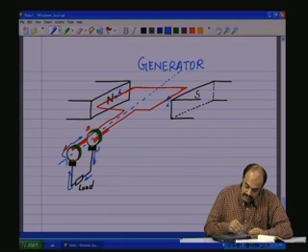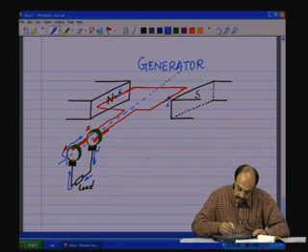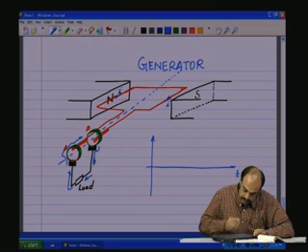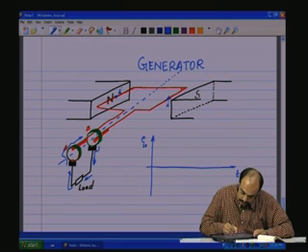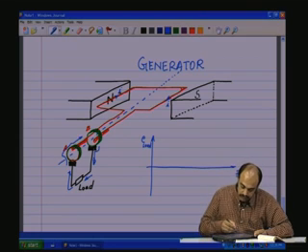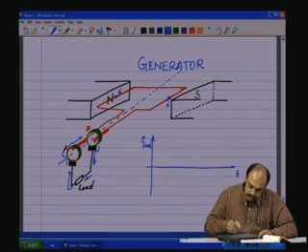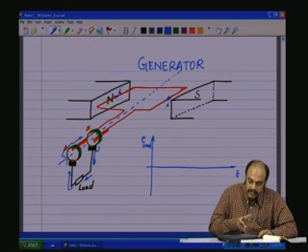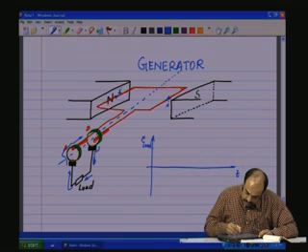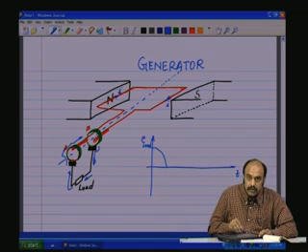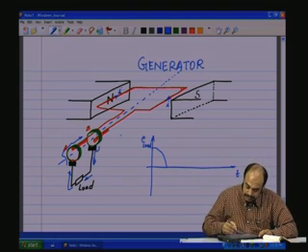Induced output here. So, as the whole coil is rotated, we see that the voltage across the load, E load, which is the induced EMF across the brushes, starts with, in this position, a maximum, because the north and south are going to produce these aiding currents, and as it starts rotating and takes an orthogonal plane, this is going to pass through 0, because when the coil is in a plane perpendicular to the plane which is right now shown, it will be 0, because there is no flux in the perpendicular plane.